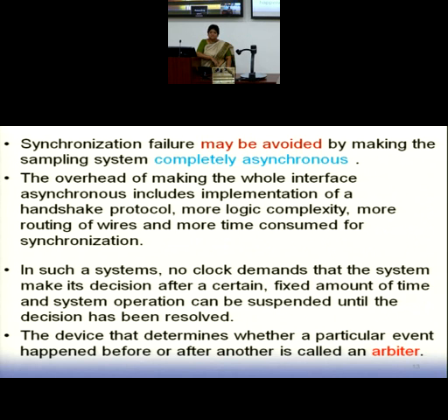So in the early 1970s, two scientists did a thorough study of it, and reported that a major problem is synchronization, which should be avoided, and hence a lot of focus went into designing good synchronizers. A good synchronizer is actually nothing but a kind of arbiter, where you have two competing inputs. Here also you have two competing inputs, one is the clock, the other is the data.